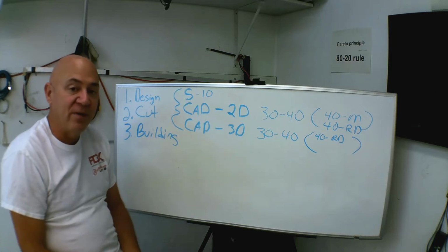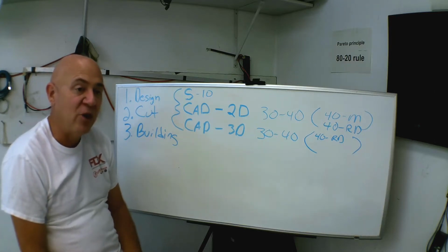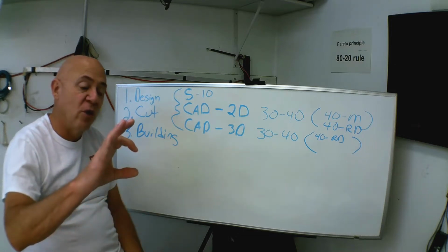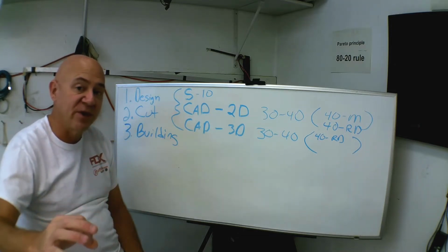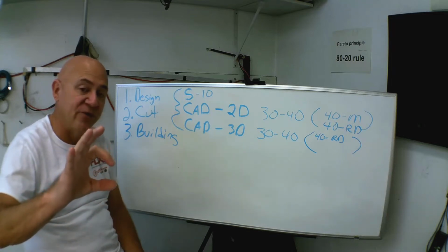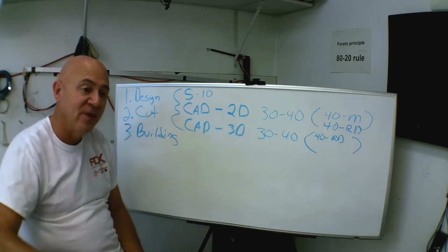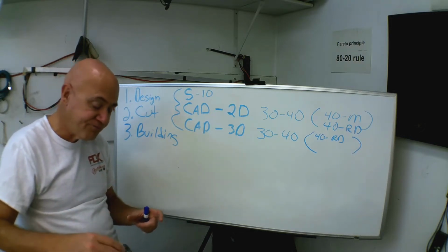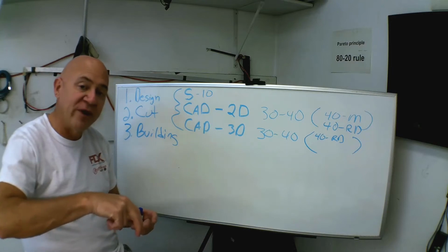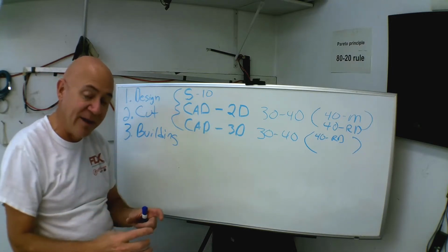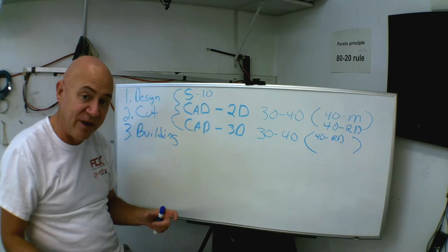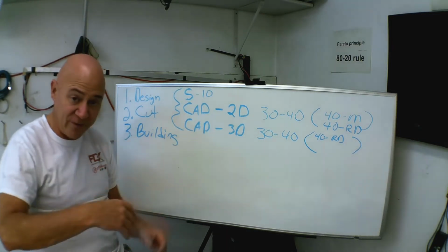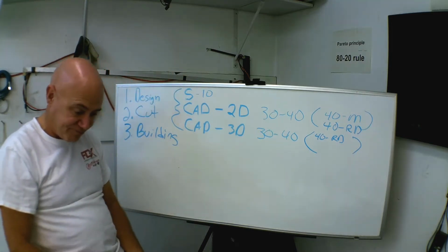And you are going to build an airplane with a 20-foot wing, and you're going to use pink styrofoam like I am. You are going to drill holes through it where your spars are going to go, but you're going to have these holders that you 3D print that hold the spar in place. So you take your pink styrofoam, and you go through 3 ribs at a time cutting holes because you've got to line it up as best as you can. You've tried to build a jig, and you go through. You get 20 of them cut out. You throw them to the side.